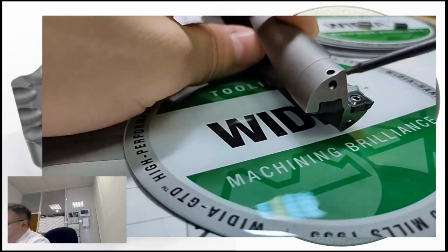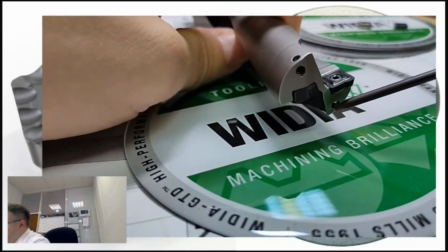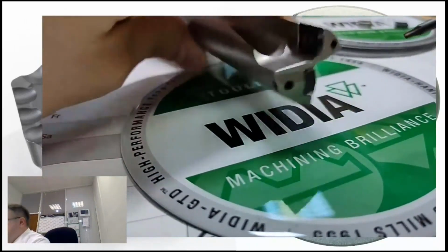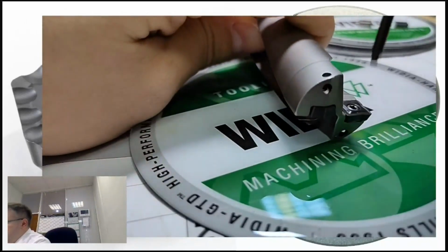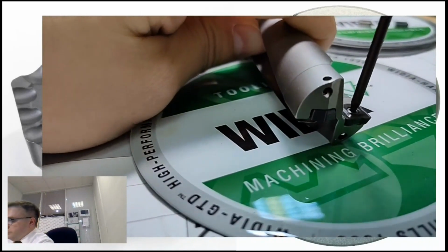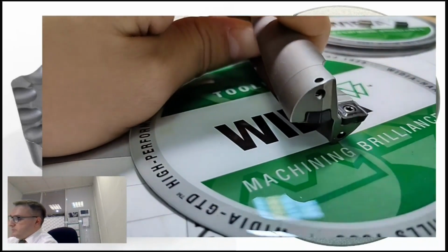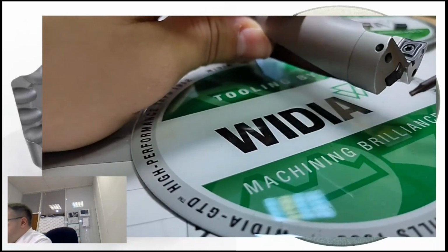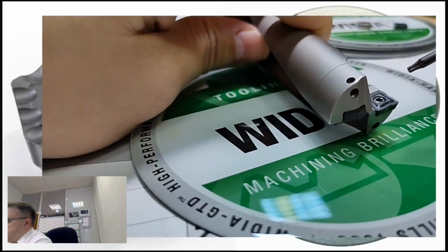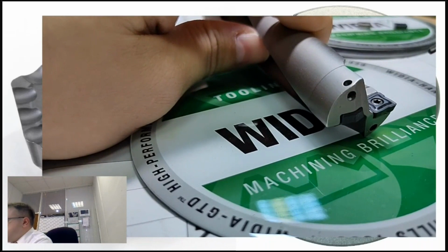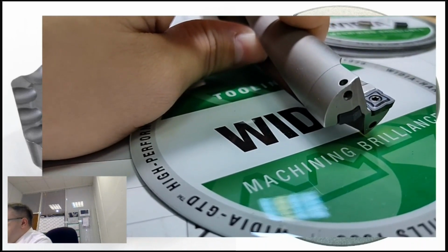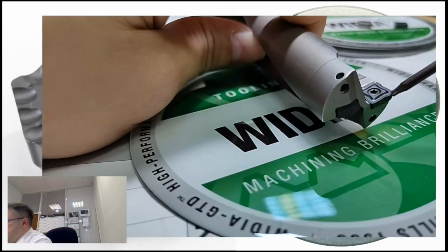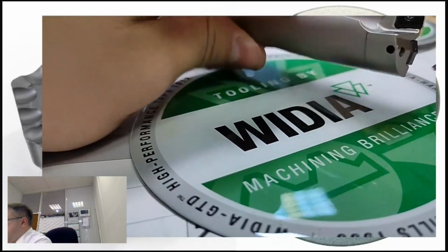And here you can see also the coolant channels, one coolant channel and the second coolant channel. Sometimes you can see other channels, but they are technical channels for producing a hole for the clamping fluids. Both inserts can be clamped by screws. There can be more inserts on one side of the drill and on the other side, but you'll see them only on special drills with bigger diameters, for example 80 millimeters, 90 millimeters, and so on. It's possible to put another insert on another level.